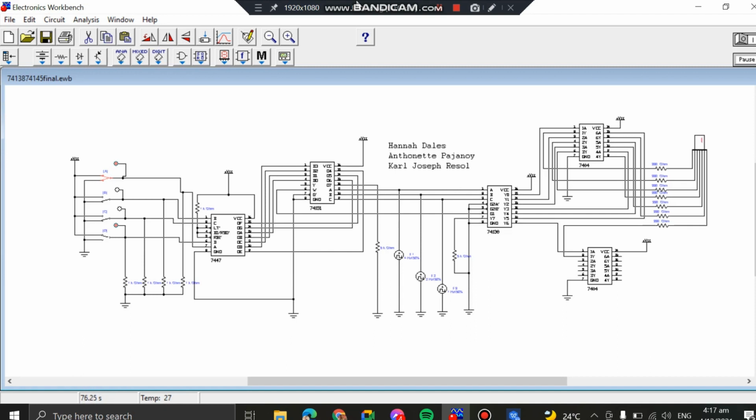The frequency of the clock is also important for the multiplexer and demultiplexer to clearly transmit the desired data and display it on the LEDs. Since we analyzed the circuit, the input line of the multiplexer 74151 is active low, so we use the inverted output W of the 74151 to drive the G1 input of the 74138, which is active high.